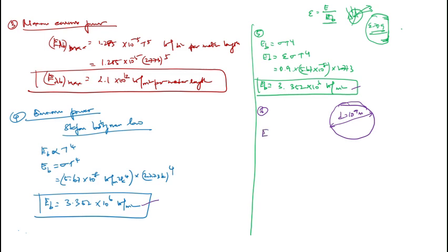So here E_B is equal to sigma T to the power of 4. If emissivity is given, E_B is equal to epsilon sigma T to the power of 4. If the area, like the diameter, is given, E_B is equal to A into epsilon into sigma T to the power of 4. You already know sigma T to the power of 4, which was found in the previous problem.